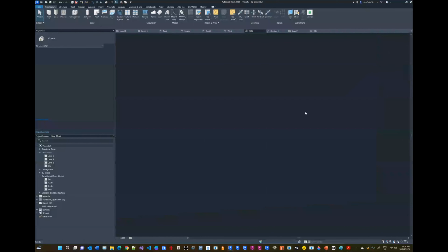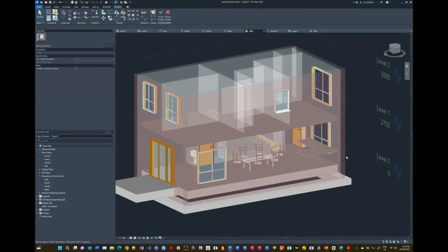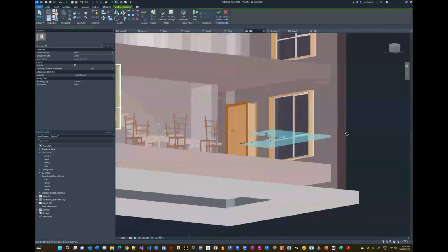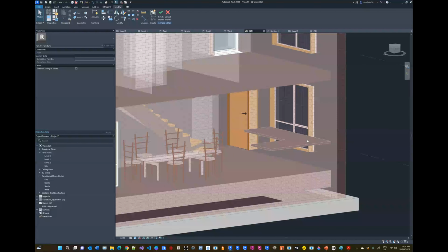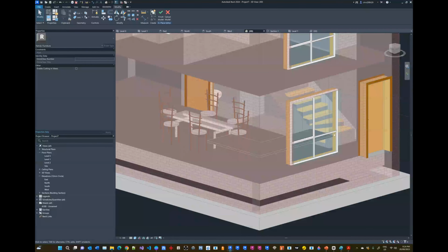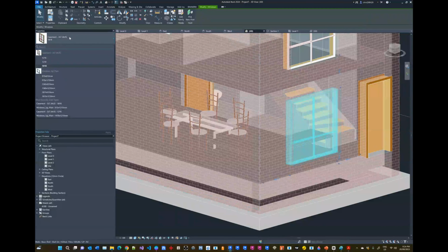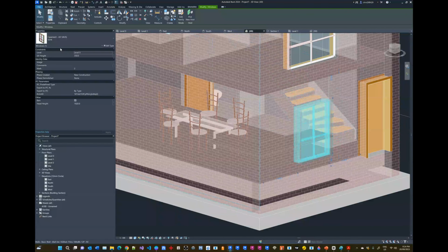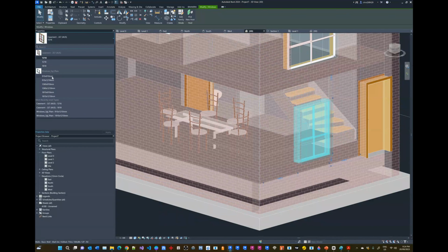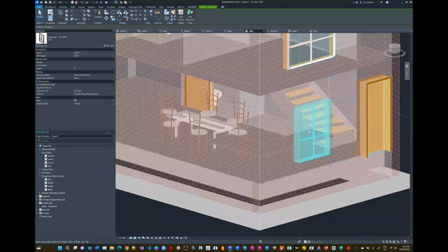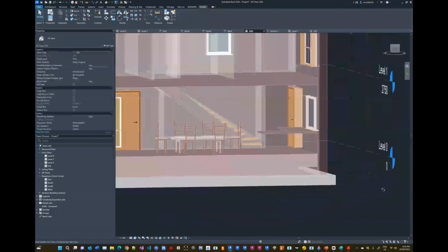And sorry, this is the wrong model. Let me go back to this model, which means it's going to sit right there. Okay, so that is how I modeled that countertop. Notice it's kind of interfering with my window here, which is probably not what would be the case. So if I just click on finish model, if I change this window type perhaps to something a little bit smaller, that's not the one, maybe something like that, and we move that sill height, that's probably going to be better.